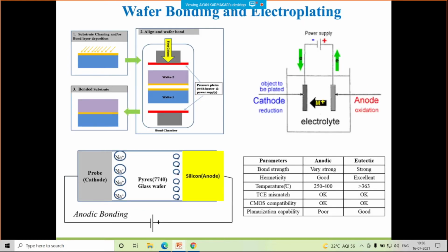And if you want a thicker substrate, if you want to make some filter, a high Q filter, then you have to think about how to maximize the Q factor. Because you know from the very basic theory of Q factor, if we can maximize the volume of the whole resonator, then there is an option to maximize the Q factor also.